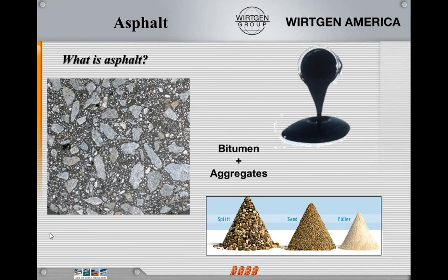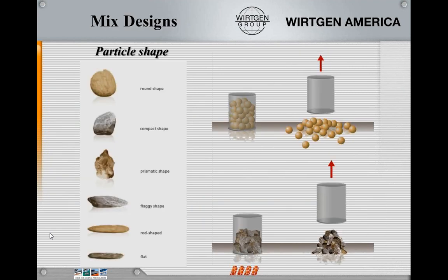And asphalt, really what it is, is basically just a combination of different size aggregates with a certain type of bitumen added. Now, we also don't want all those particles to be round marbles because we'd never be able to make a pancake out of the roadway. We'll make a 15-foot road out of a 12-foot road. We want some fractionation to our aggregates so that we can have some aggregate interlocking and get good load-bearing capacity of that material. We want a little bit of round stuff in there just to help get the compaction in shape, but we want more aggregate interlocking for the bracing. Not too many flat and elongated pieces because once we vibrate on top of those, they break apart.